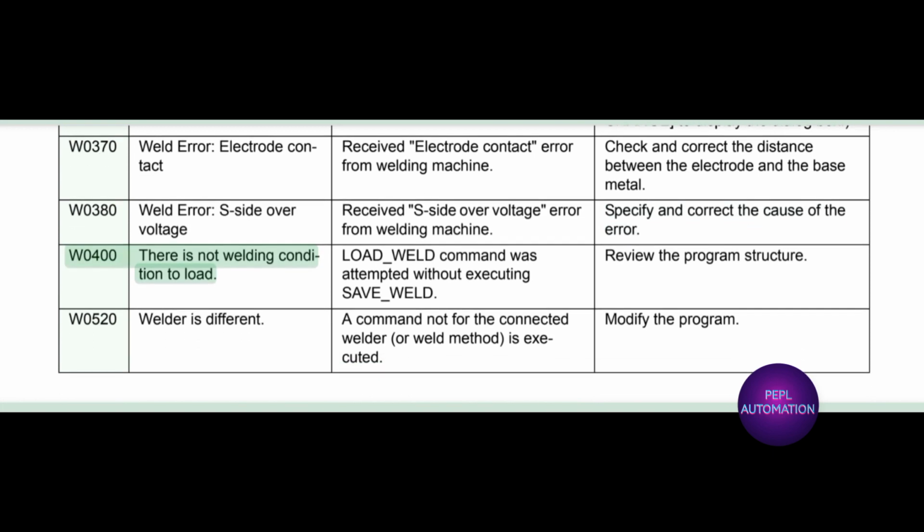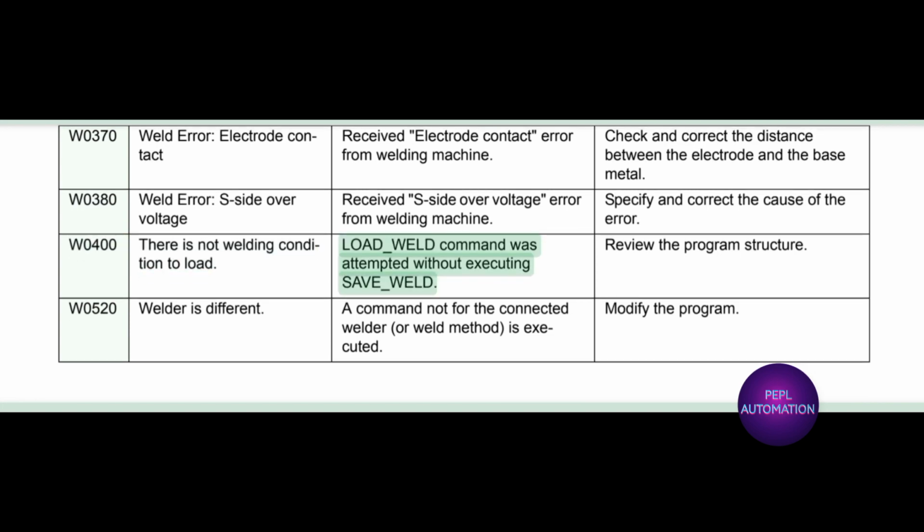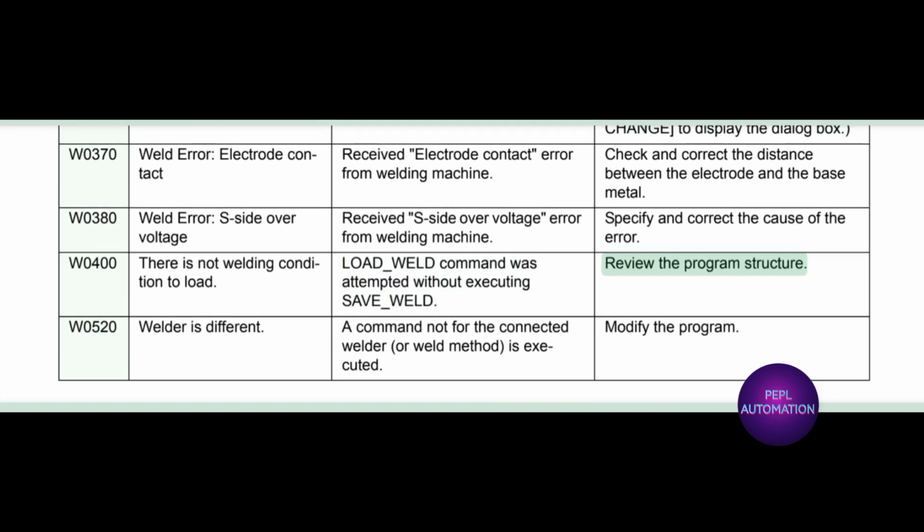W0400 there is no welding condition to load. Load_weld command was attempted without executing save_weld. Review the program structure.